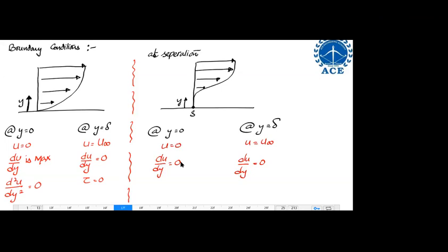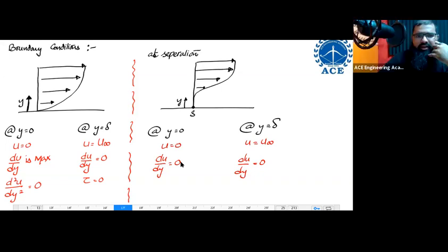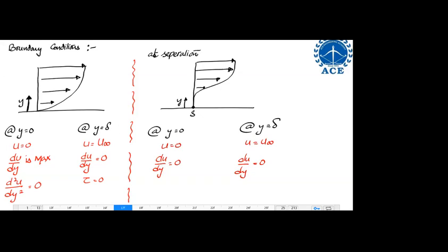That's why, sir, we are not able to visualize the streamlines. Whatever results they are getting, on what basis are they getting these results? To locate the streamline is not possible. But if there is a particular velocity profile, we can still imagine the streamlines by the equation, right? Sir, but one streamline we will get, but adjacent to it the other streamline location we don't know. No, we can get an infinite family of streamlines.